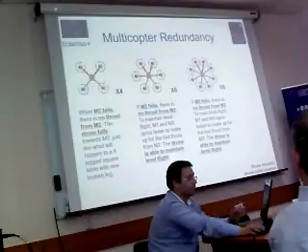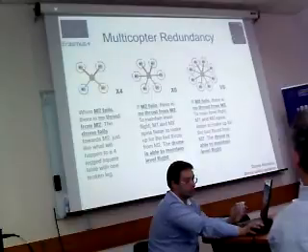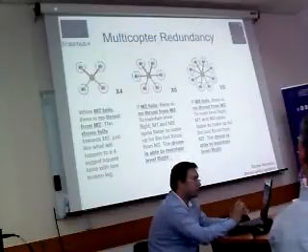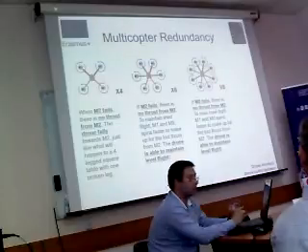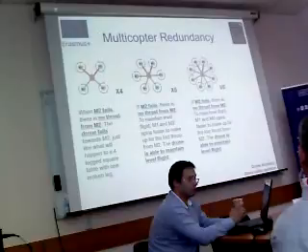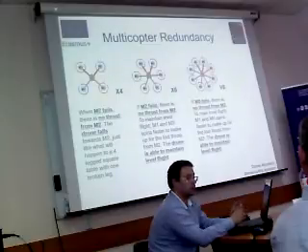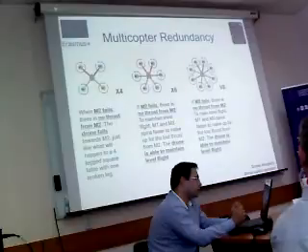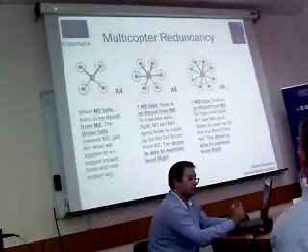So the other solution is the hexacopter. This is also a very popular design, and it is really used when the drone needs to carry a pivotal load. So motor M2 spins clockwise, which generates an anti-clockwise moment. And when M2 fails, there is a loss of anti-clockwise moment, so there is a net clockwise moment. To make matters worse, while M1 and M3 spin faster to compensate for the lost thrust, we create more clockwise moment.